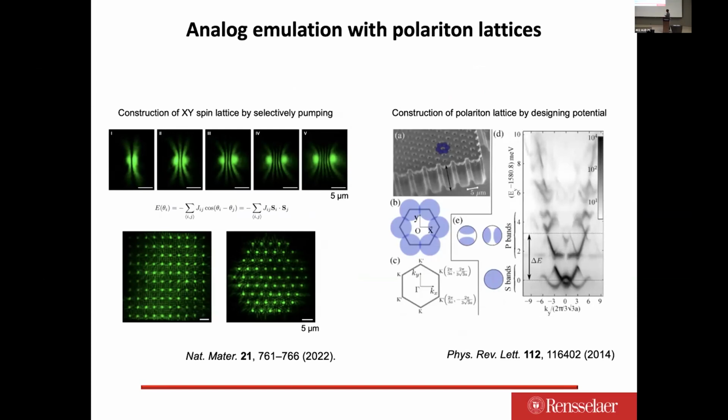This is traditionally done in gallium arsenide by etching a really deep quantum well with high aspect ratio. That is not easily achieved, especially when etching very small features. The defects on the edge start to quench the quantum well behavior and make the experiment really hard to interpret.